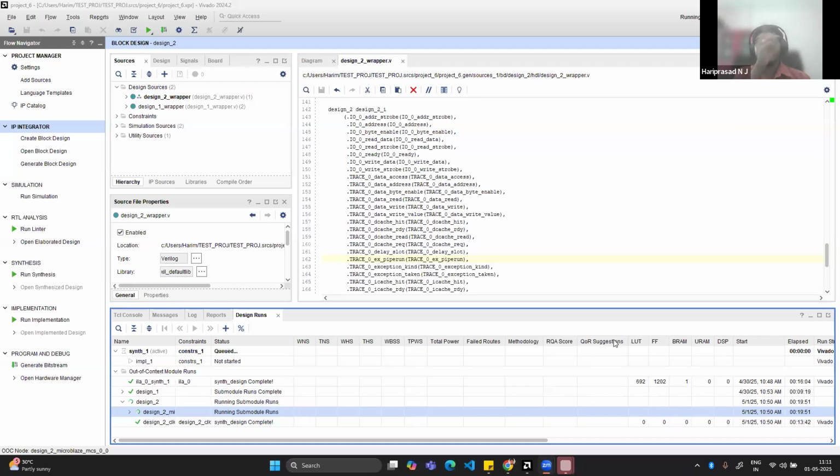Usually we configure either through JTAG, which is one way, or we remotely upgrade, for example using some UART interface where some processor configures it. Ideally the architecture is that the bit file is stored in flash. One way is remote upgradation, meaning the flash upgradation. But inside the FPGA, that is dynamic configuration. Ideally, each bit, through JTAG or the quad SPI core, is going to be configured bit by bit. Every bit will be reconfigured.